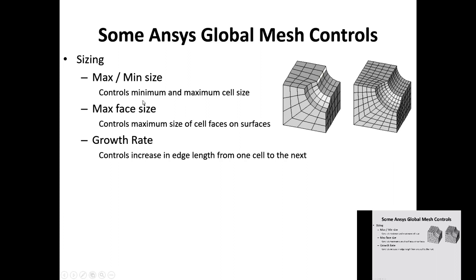do the volume mesh. And then also you can give what you call a growth rate. A growth rate is defined like this. Now, for example, in here, you can see that the size of the grid cells are increasing along that line. That means it has a growth rate. So usually you can have a growth rate of about 1.1, or maximum 1.2.